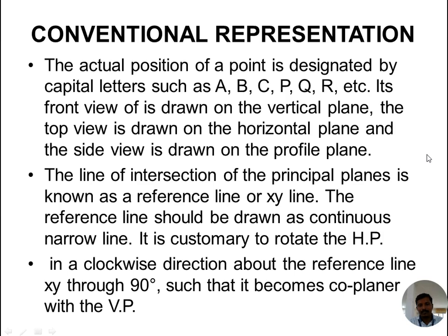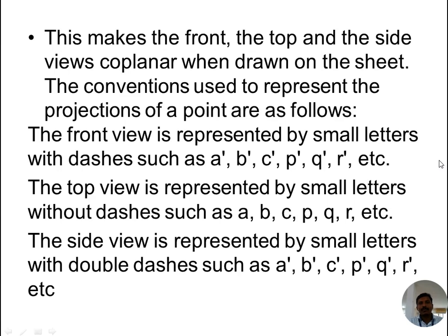It is customary to rotate the horizontal plane in clockwise direction about the reference line XY through 90 degrees such that it becomes coplanar with the VP. This makes the front, the top and side views coplanar when drawn on the sheet.